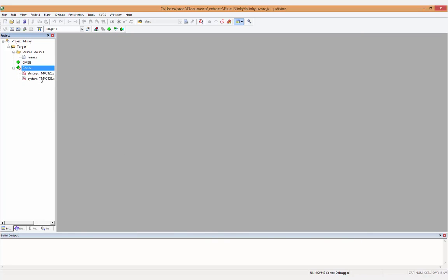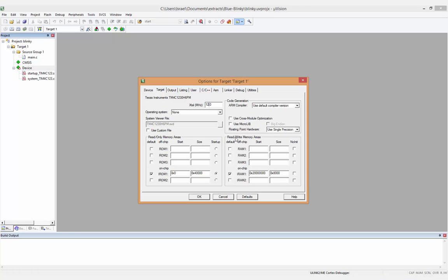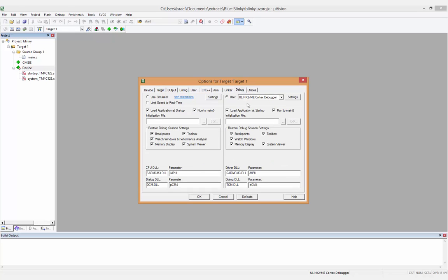Yes, so now let's set up other board parameters like the debugger interface we use and the frequency. We click here, the target options, and we change the frequency to 16 megahertz, and we come to the debug tab and we select our debugger. Remember when we said the ARM company does not produce microcontrollers, but it produces designs and licenses these designs out to various companies.